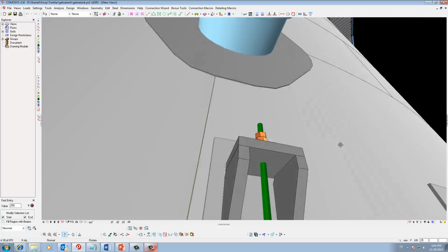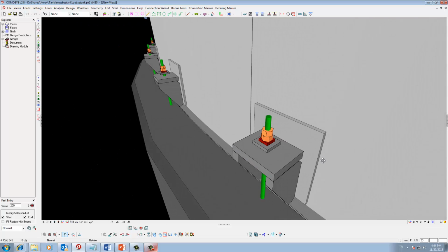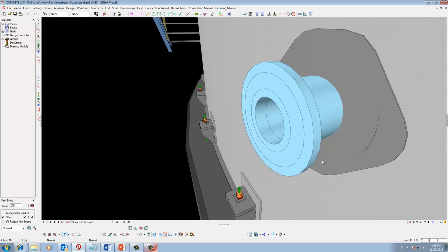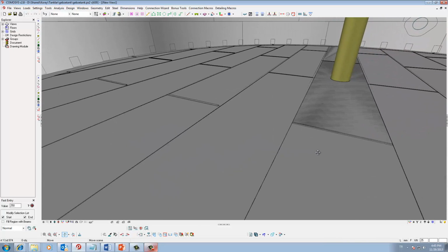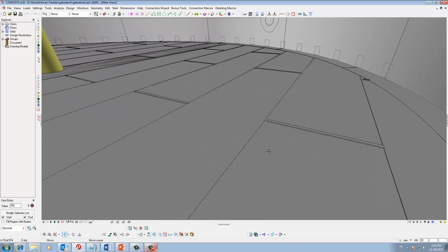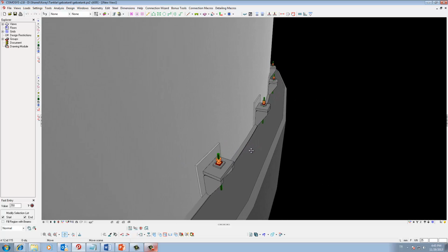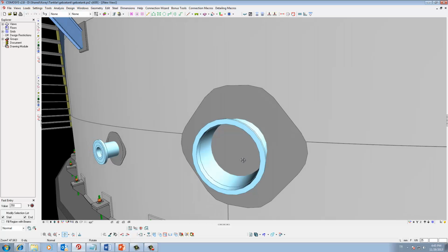Various options are available for modeling the anchor bolts, which resist the wind and earthquake forces. The base of the tank, along with the main shell, is one of its most complicated parts. Staggered plates are used to minimize failure risks, and fine-tuned patterns minimize the wastage.